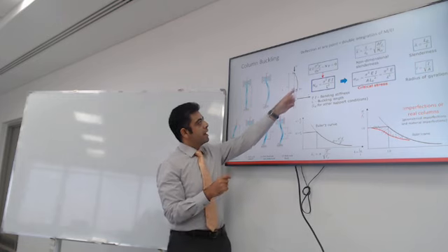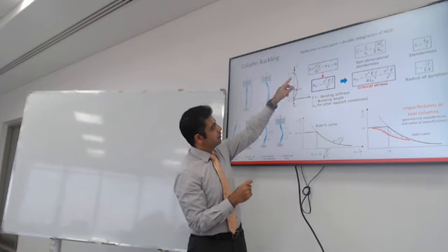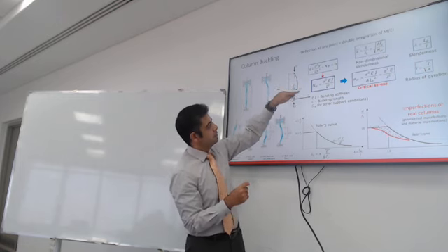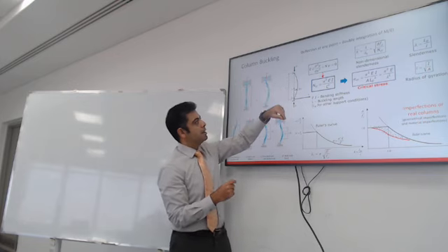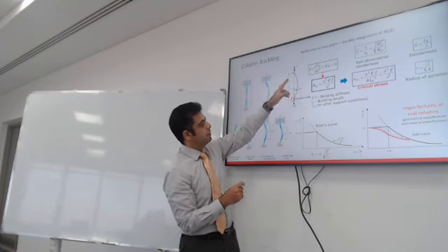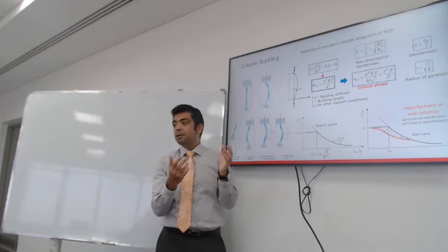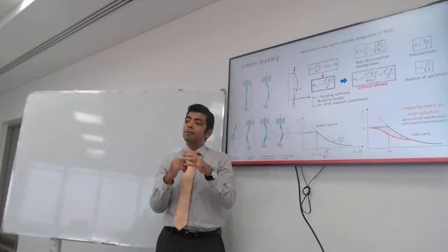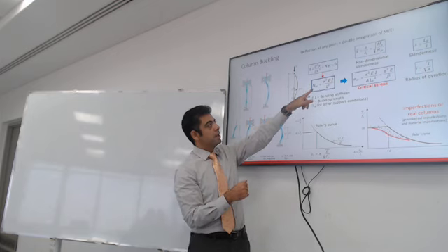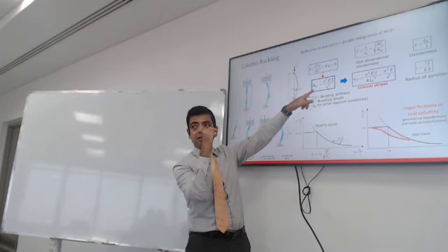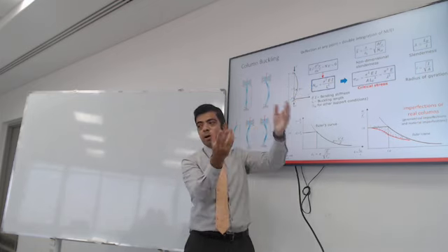The moment at any point is the axial load multiplied by the distance y, and the double integration of the bending moment gives the sideway deflection. So we can solve that equation to get the critical axial force that will cause buckling.